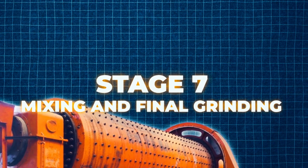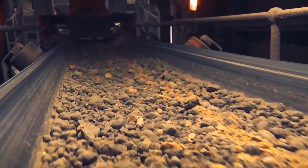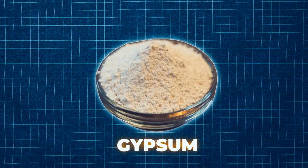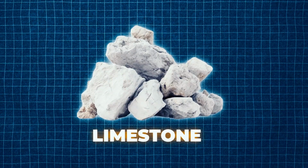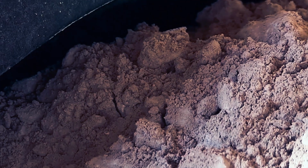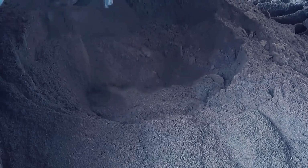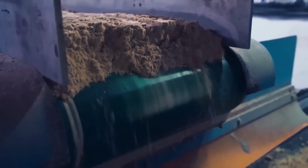Stage 7. Mixing and final grinding. When the clinker cools down, it is mixed with a number of other materials, such as gypsum, fly ash, and limestone. These additions help control how long cement takes to set, prevent fires, make the cement easier to work with, and lower its shrinking, among other things. A ball mill or a machine like it takes the clinker and chemicals and grinds them into a fine powder.